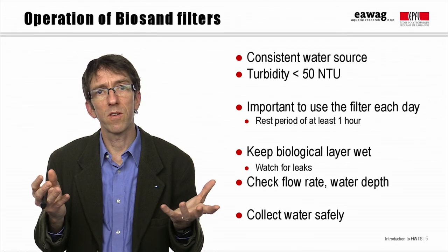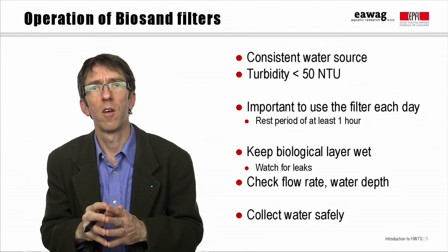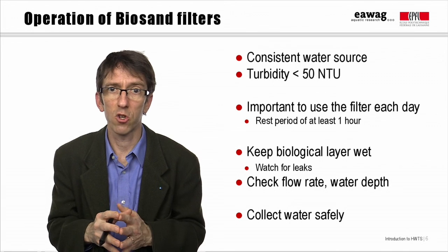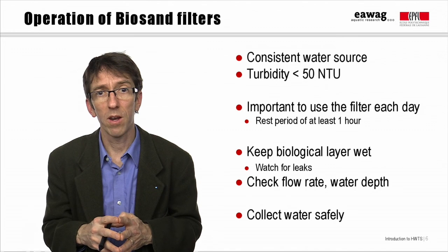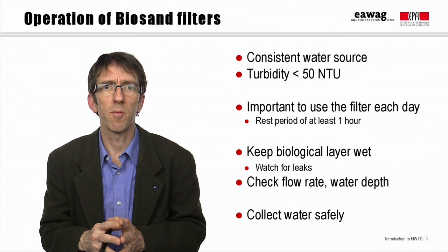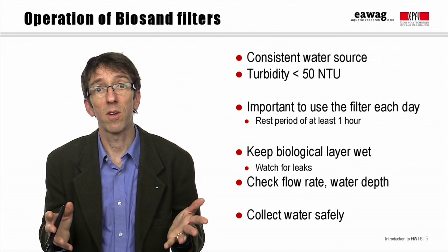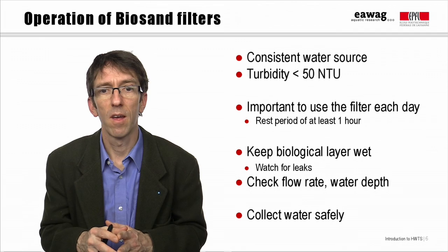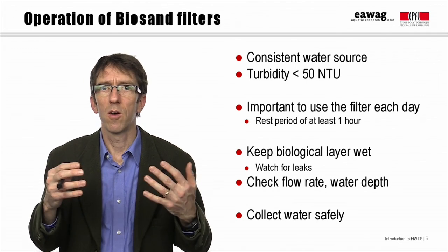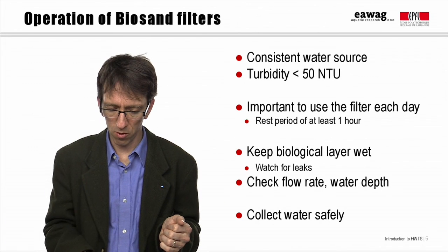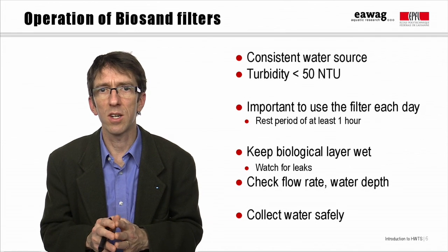Similarly, it's important to make sure that the biological layer is always wet. The Schmutzdecke will die if it dries out. And many of the systems have a hydraulic control so that the outlet is above the sand layer, but still it's important to check for leaks and make sure that the sand is always wet. Likewise, it's important to check the flow rate. If the flow rate is too fast, treatment may not be effective. And if the flow rate is too slow, it might be time to do a cleaning. Finally, biosand filtration doesn't give any residual disinfectant, so it's important to collect the water safely in a safe storage container and manage it hygienically after treatment.